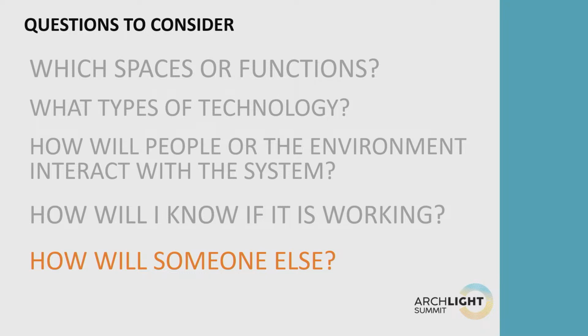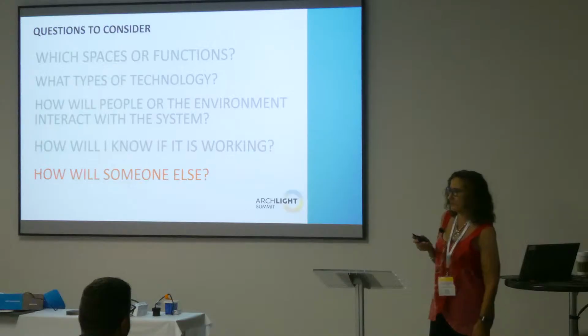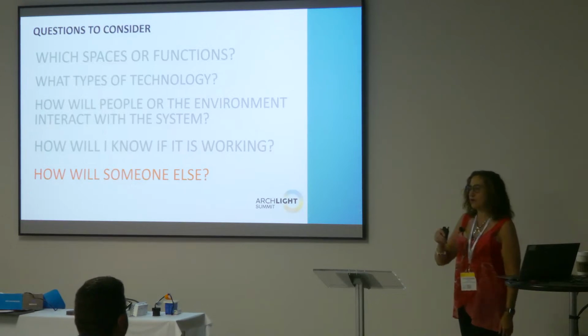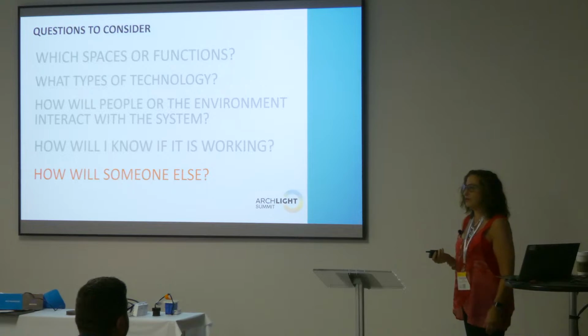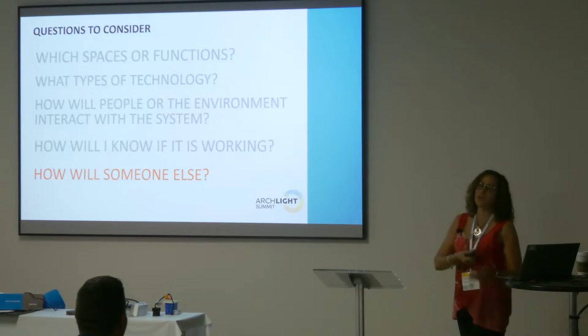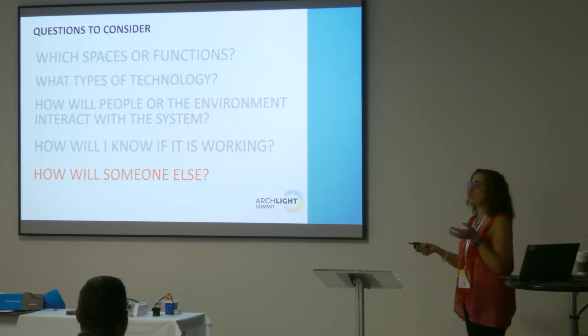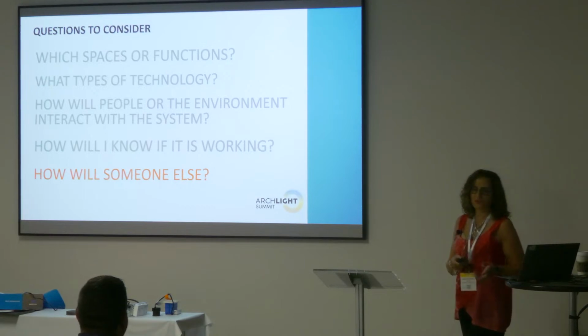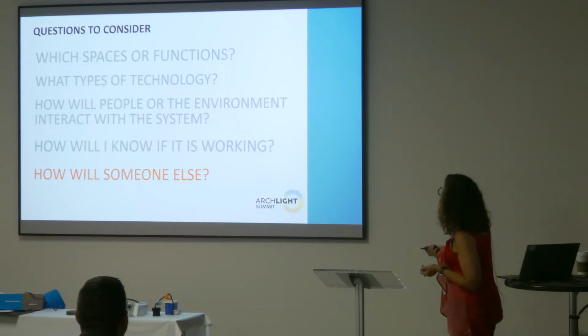Because for LEED, one of the most important points in LEED is enhanced measurement and verification, or commissioning. You cannot commission a system if you don't know what it's designed to do. Commissioning is not about startup. Commissioning is about making sure that what the system was designed to do, it is doing. And to do that, you need measurement and verification. And you can't have measurement and verification if you don't know how somebody else is going to measure it. Does that make sense so far? All right, moving on. Maybe.